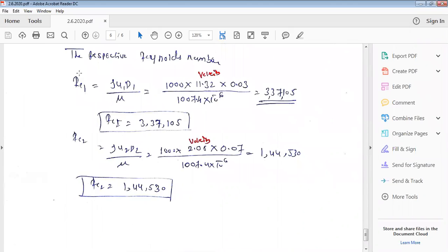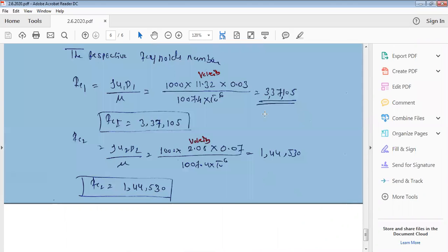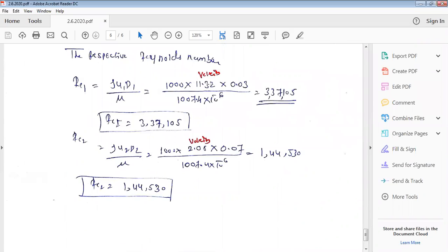Now just see, this is a dimensionless number. As the number is more, you can say that the velocity is more. Whenever the number is small, the velocity is less. That's why the Reynolds number has a small value here and a bigger value there. Depending on these ranges, we are going to multiply it with another dimensionless parameter, the Grashof number, and when you multiply these two, you decide the Nusselt number.